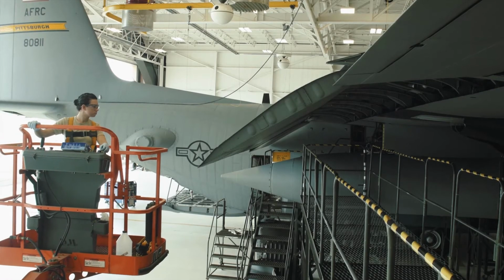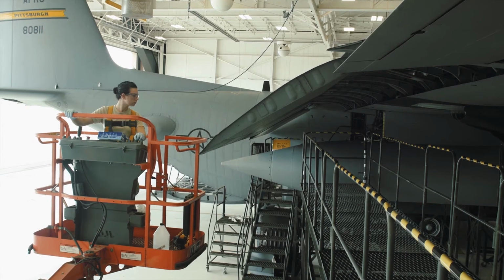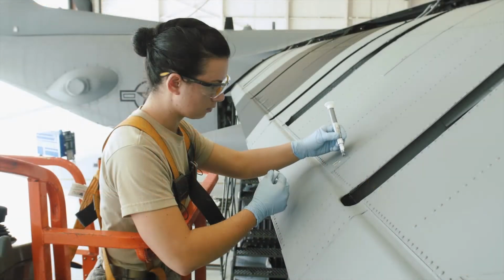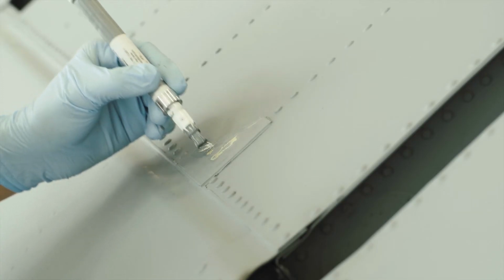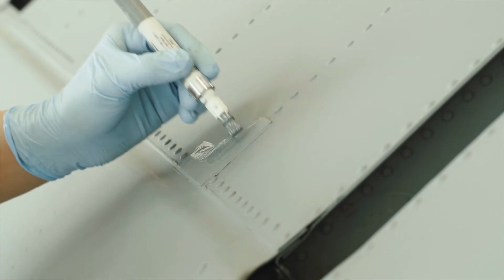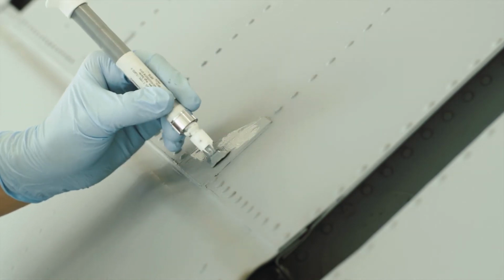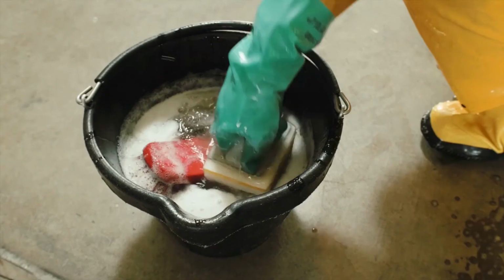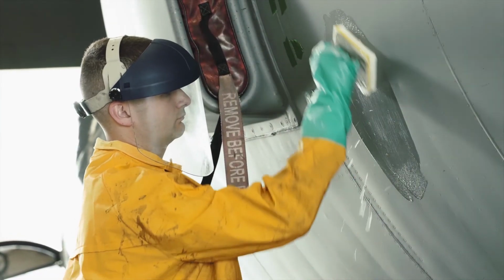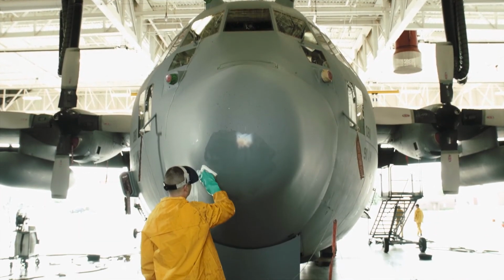Since these coatings are the first line of defense against such corrosion, you should frequently inspect aircraft and equipment to identify any damage to their coatings. You should document the type and extent of such damage so authorized repairs can be made and/or touch-up materials applied. Preventing corrosion is much more cost-effective than treating or repairing materials damaged by corrosion. It is important to properly wash aircraft and equipment at specified intervals and frequently spot clean to remove corrosion-causing contaminants and to provide clean surfaces for accurate corrosion inspections.